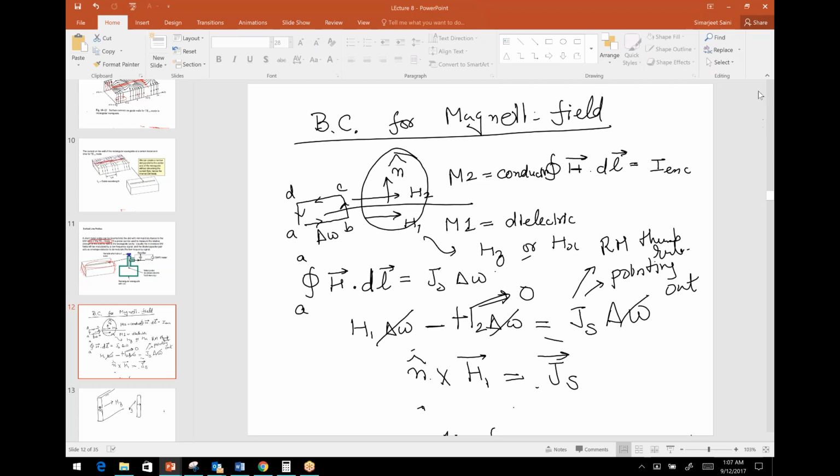Yes, sir. So what are the metals that are used to construct the waveguide? What metals do you use? It depends a lot on the frequencies. For low frequencies, meaning up to 2.4 gigahertz, for very low frequencies, a few hundred megahertz, it could even be steel.